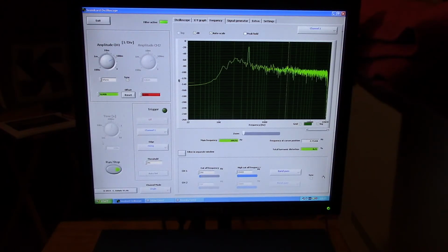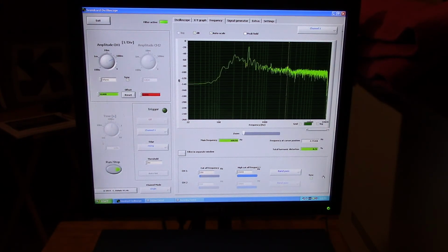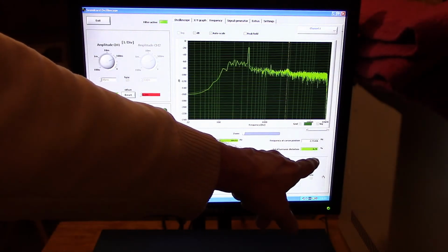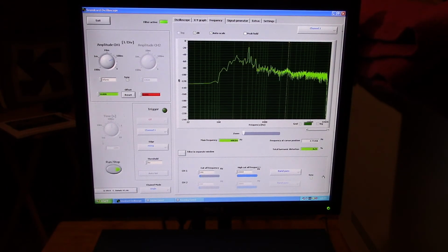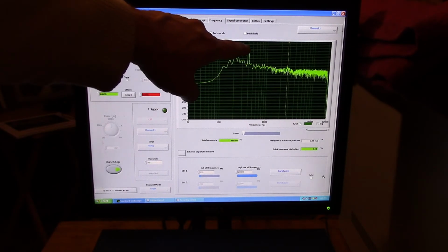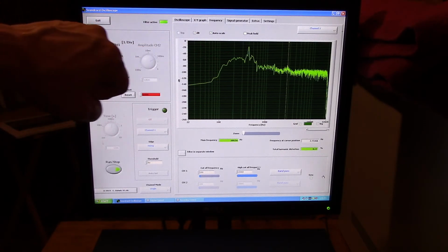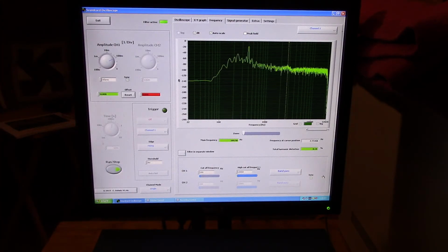The sound card oscilloscope application also has the ability to measure total harmonic distortion. If you're measuring an amplifier, something like that. With headphones, it's less meaningful because most of this distortion is going to be introduced by the sound card itself, not as much by the microphone in the headset. As you'd see, it's reading between 0.2 and 0.27% total harmonic distortion. So this is the main carrier at 400 hertz. So you would see replicas of this if there was harmonic distortion. We're really not seeing anything.